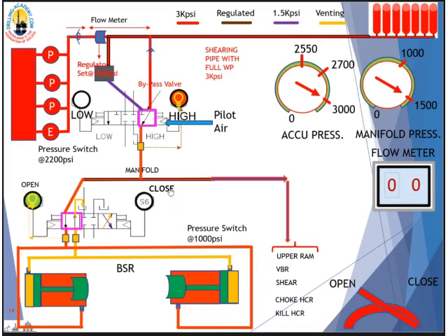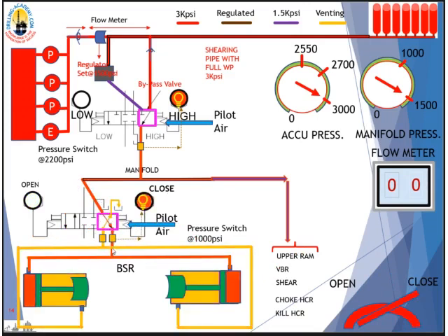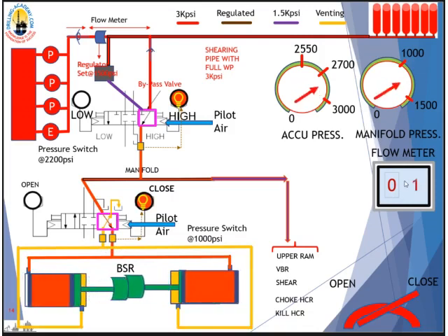Let's take a look. Air pilot acting here, okay, the valve sleeve moves, fluid comes down here, the line changes state, all right, moving in here, and you see the flow meter runs, all right, the pressure gauge drops, pumps run, and the pressure gauge comes back up, the flow meter stops running when the BOP finishes the function here, all right, and the valve handle shifted from open to close.